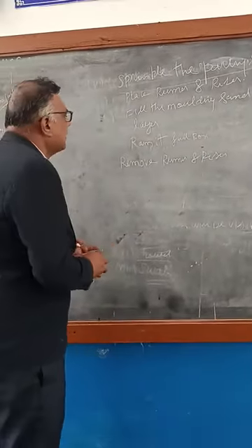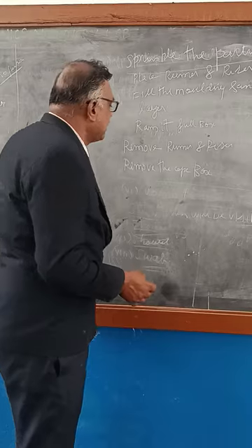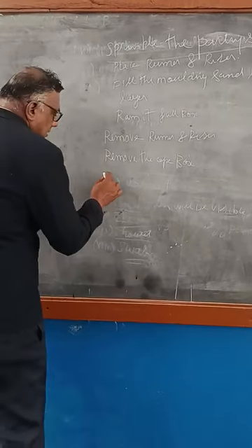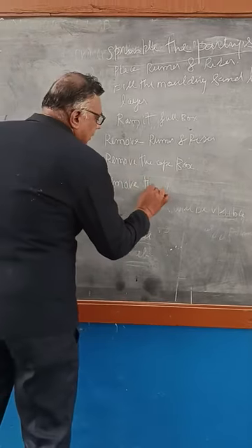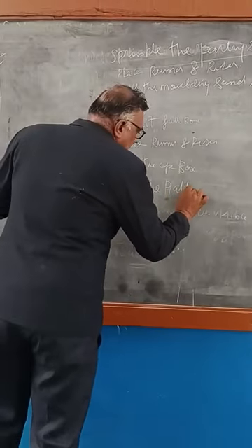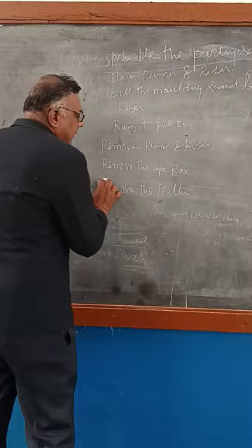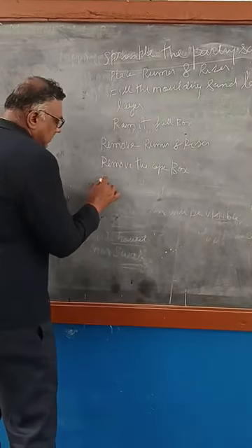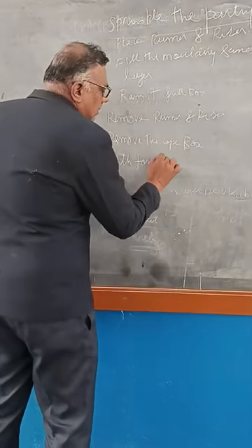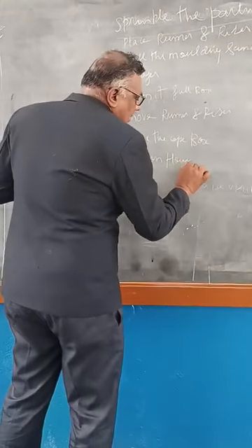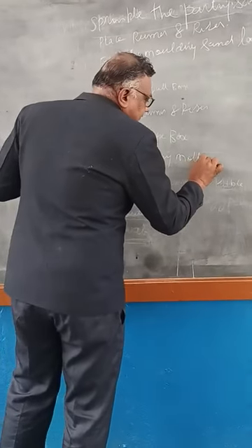Now, after removing this box, the pattern will be visible. Right? The pattern is visible. Next, remove the pattern. Or before removing the pattern, you have to make a path for flowing molten material.